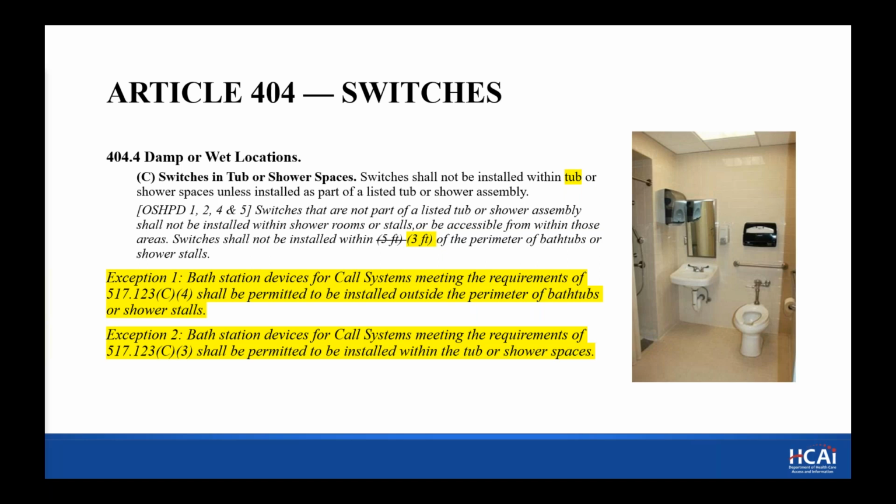We've had internal discussions, and our understanding of the shower is the threshold of the shower. So regardless of whether it's a shower head that can be manually operated, or the drainage system in the bathroom, or the lack of a threshold at the shower area, the threshold of the shower, and the devices would need to be outside of a distance of 3 foot from that area. Of course, nurse call devices, which are made and required to be in showers, are low voltage and UL listed for that use, so they are allowed.